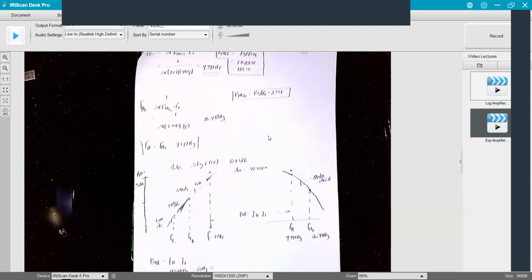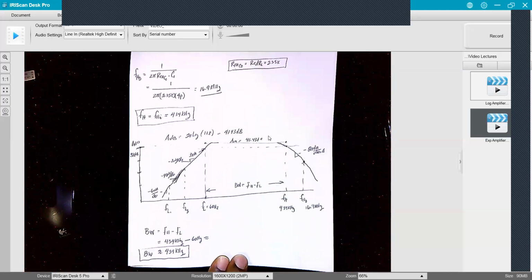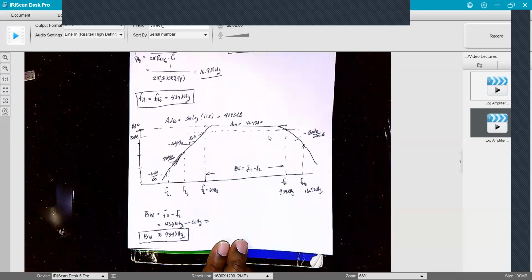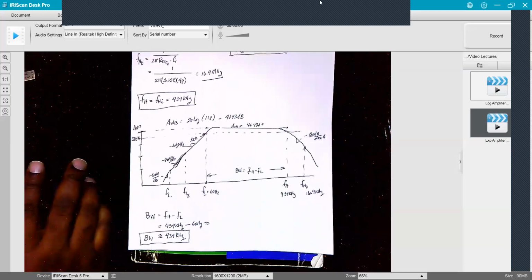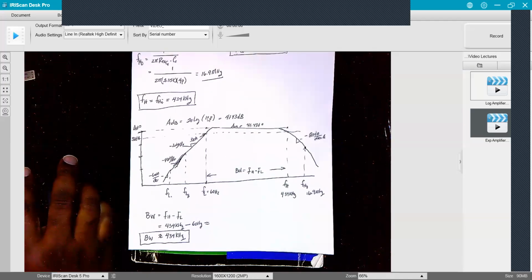And I think the last thing we asked for, and it didn't have to be very pretty, it just had to be representative because this is not to scale, was a Bode plot. So I take my 118 volts per volt for my gain, take the log of it, multiply by 20, and I get about 41.43 dB.